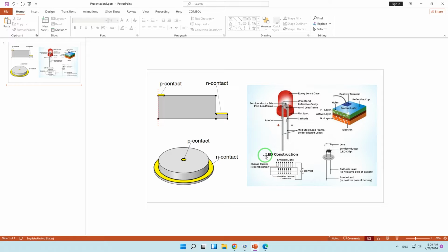The device geometry has cylindrical symmetry, which enables a 3D visualization of the results in a shorter computation time. This model shows an example of how to use the semiconductor initialization study to create a refined mesh in cylindrical geometry, and this is useful because we can automatically refine the mesh around the PN junction.